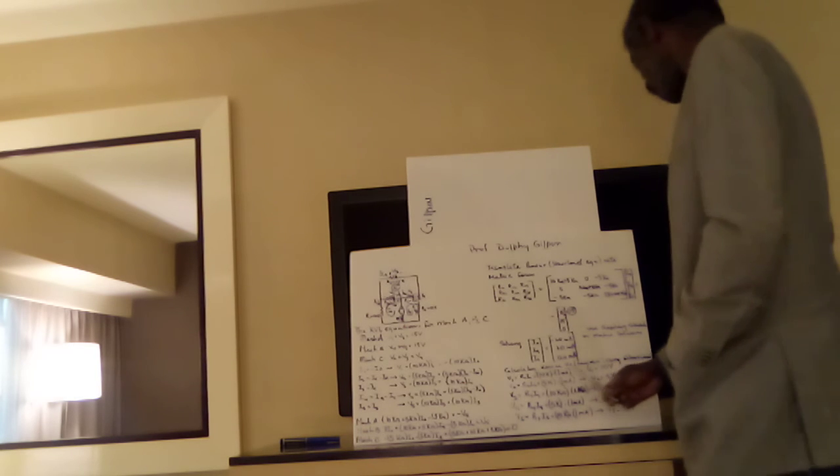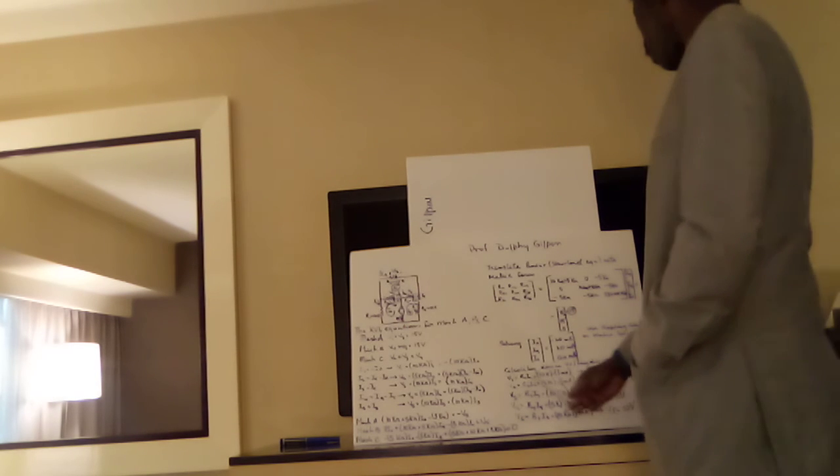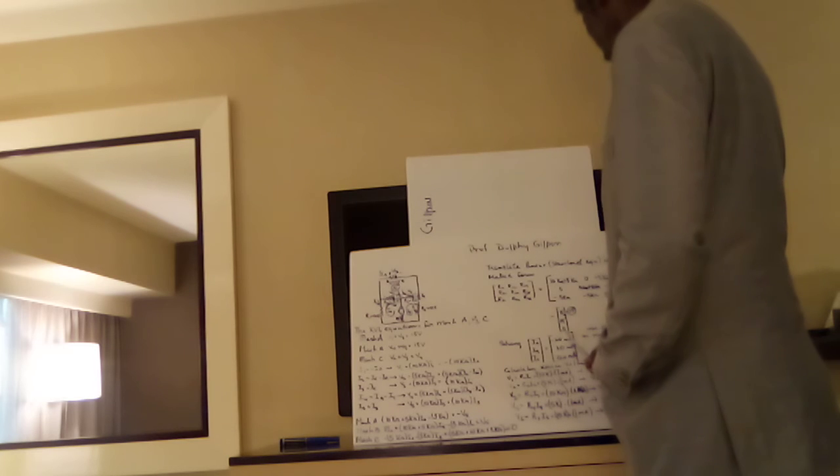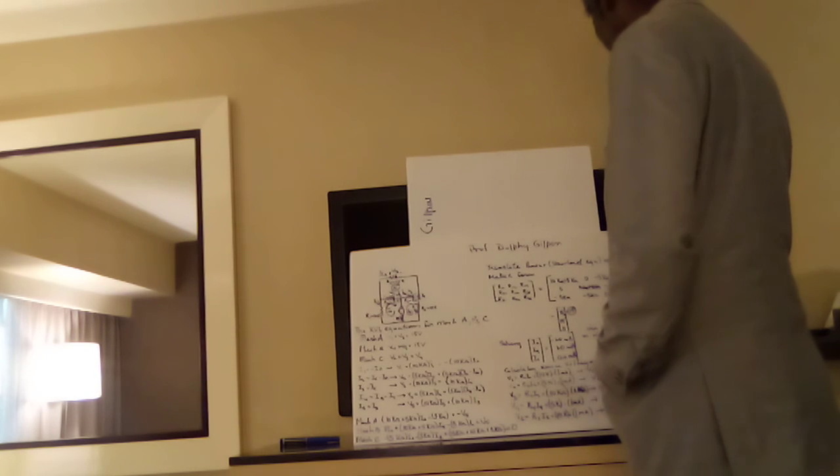Now calculating the device voltages, we use Ohm's law, and we say that V1 is equal to R1 I1, using V equal to IR or V equal to RI. And that's equal to 10 kilo ohms times 1 milliamp, which is equal to 10 volts.